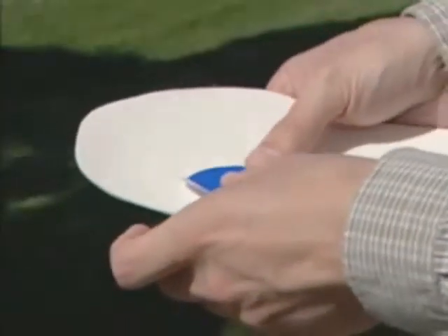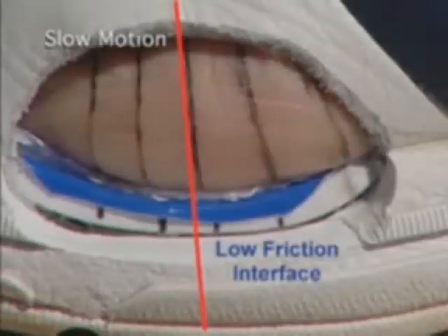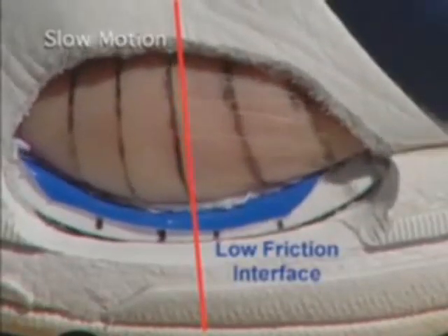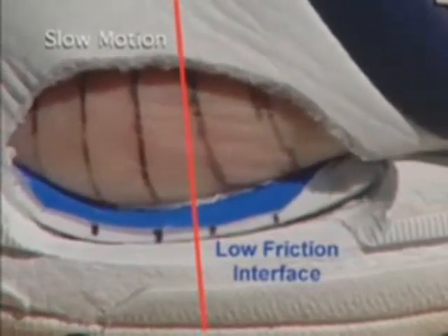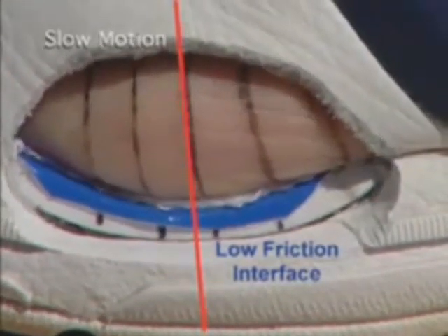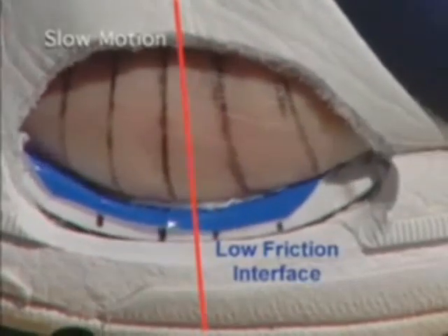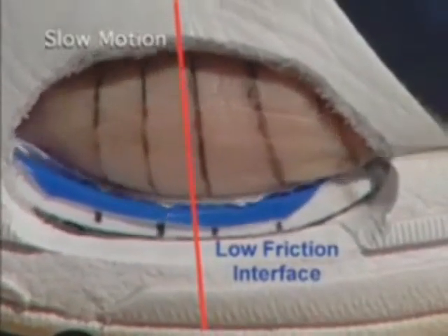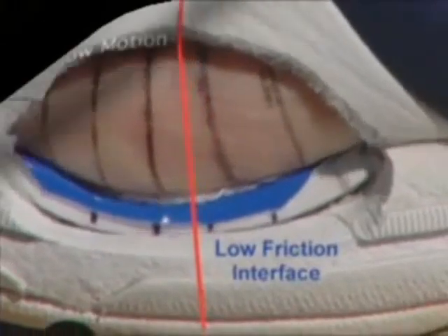The next sequence shows the application of a patch of very low friction material. Now the forces in that area are allowed to release, lowering the friction shear load on the skin in that area. You can observe how the skin slides in that area, greatly diminishing the distortion because of the lowered friction load. Here's a second look at the demonstration.